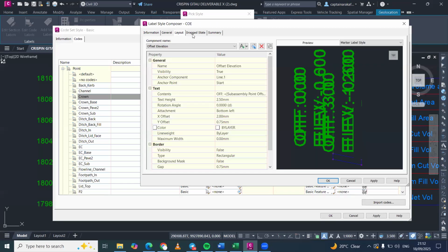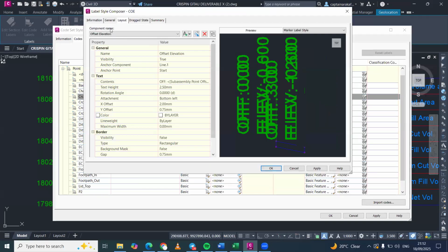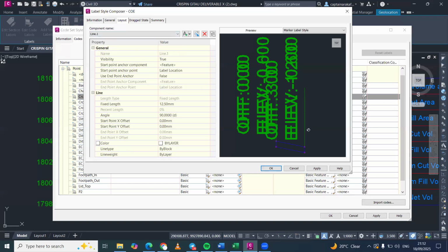Under layout, this is where our interest lies today, right? Remember when we were adjusting styles for our data bands, same procedure, nothing new, right? If you get a hang of how you can modify styles, it's just the same throughout the software, okay? So, I don't know whether I should delete or maybe one like that, so that I only remain with the line that I want, and I also remain with the component's name where I can define how it's named. So maybe for the line, I probably do not want a very long line such as that. I probably maybe have, I don't know, 2 millimeters. We will see how that 2 millimeters looks.